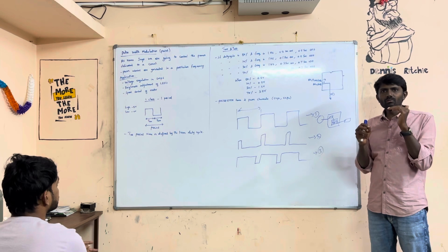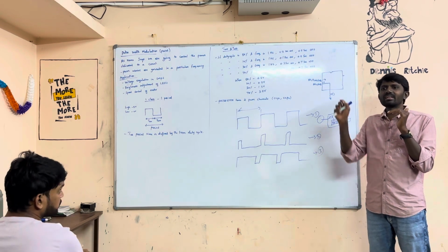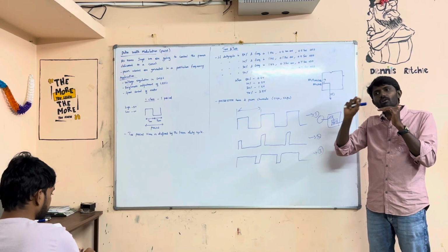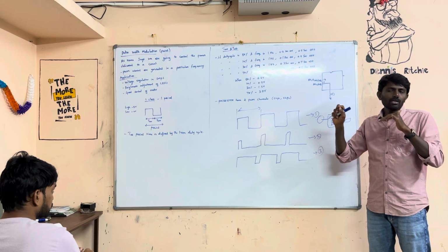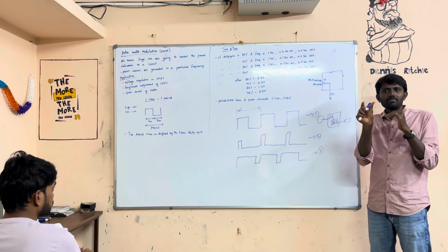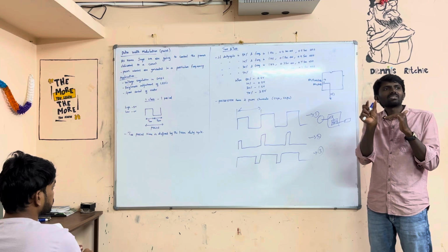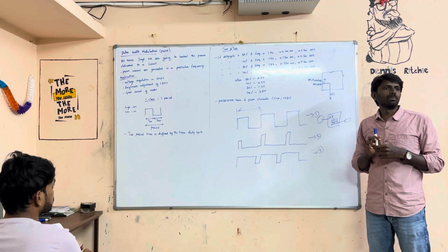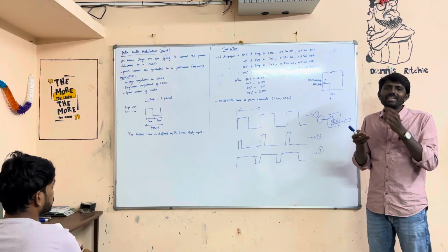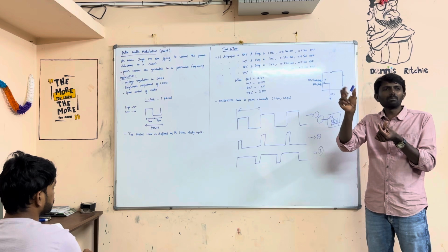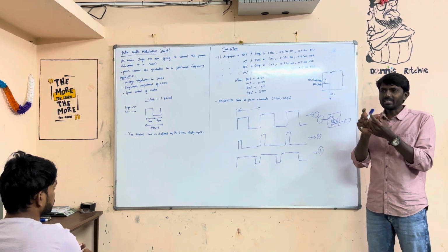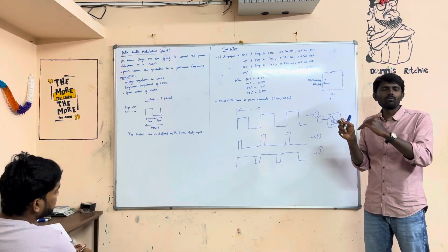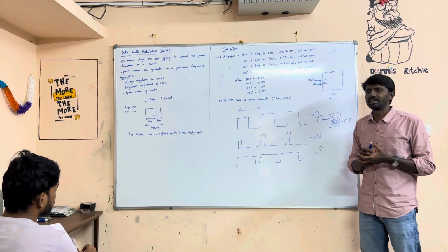Okay. So what you are going to do is there is a waveform generated. By controlling that waveform, you are going to control the output voltage. How you are going to control? Programmatically, we can control the T on time. By making the T on time some percentage, the remaining percentage will be automatically controlled, so that much percentage voltage only will be generated. If I make T on 10 percentage, that number you put into that 10-bit register, so that you will get only 10 percentage of output voltage, that is 0.5 volt only you will be getting.